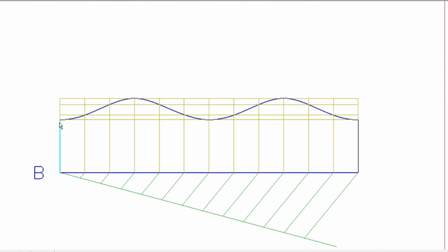Now, why must you start on the shortest end? You can technically start there as well, but if this was cut out of metal and you've got to weld, if you start at the long end, you can have slightly more welding. Now, imagine making 10,000 units like this in a factory, and you're the floor manager. That extra bit of welding can cost a lot of money if you're dealing with 10,000 units. So you want to minimize the amount of welding that would waste time and money. So we normally start on the shortest end, and that's what it will look like.